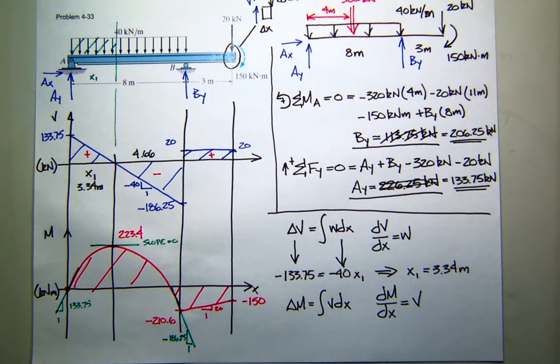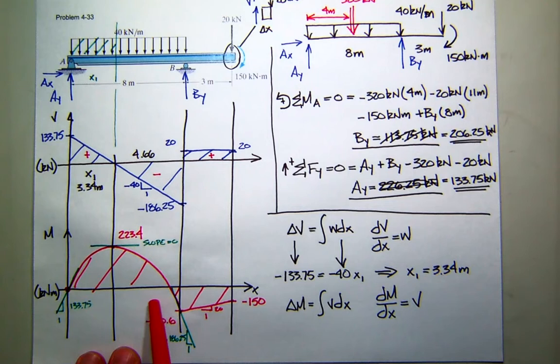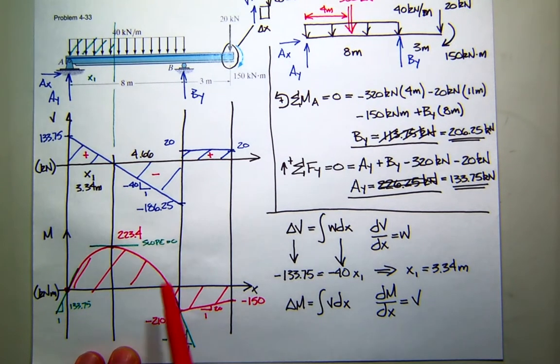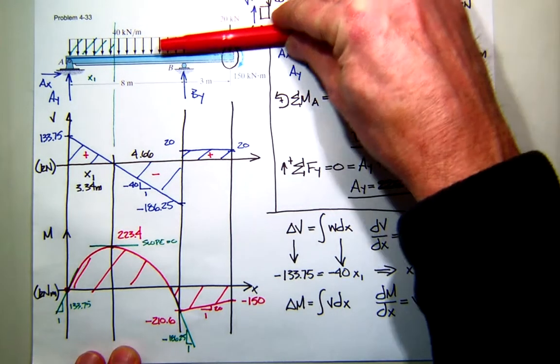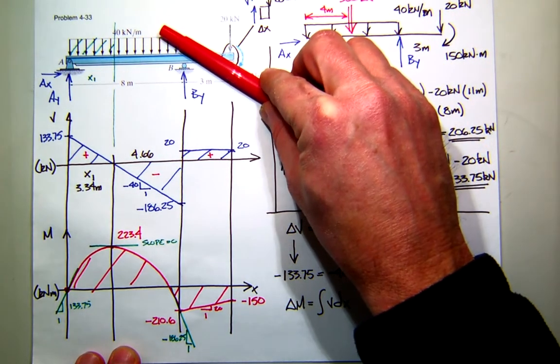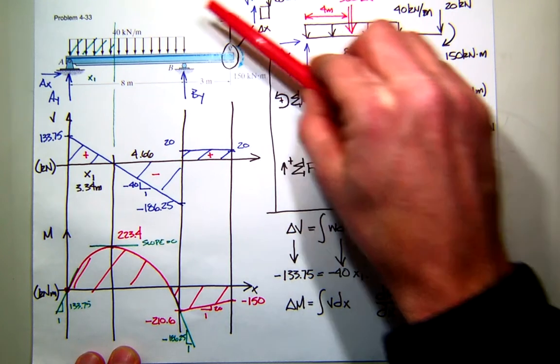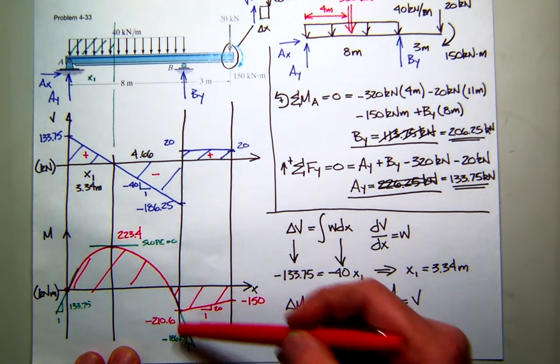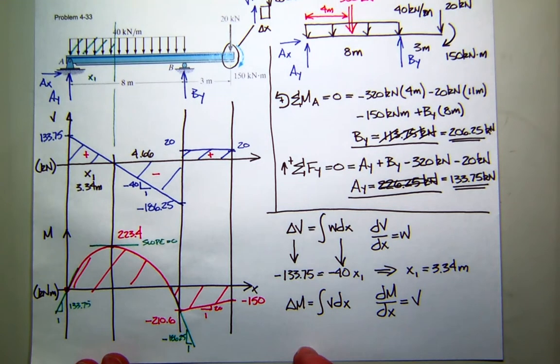In reinforced concrete, obviously, we'd have a lot of reinforcing steel in the bottom of the beam here with positive moment. And then over the support, this part of the beam was going to really bend down. So you'd have tension in the top of the structure. So you'd have to design it for what's called compression steel, but it's actually in tension at that point.